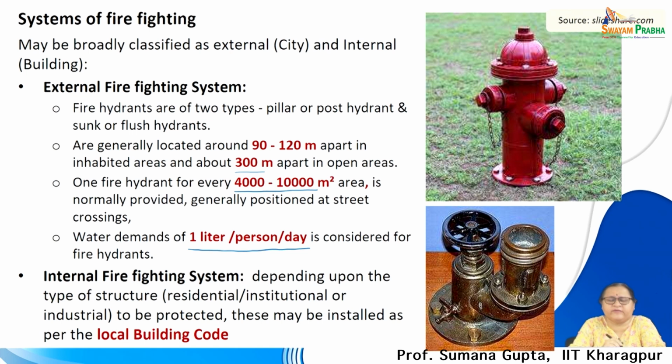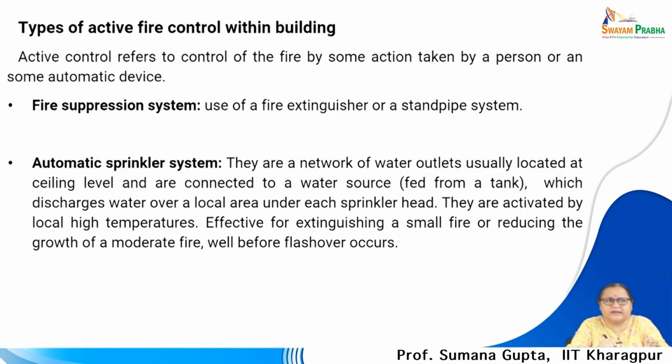However, the internal fire systems are independent of that, and dependent on the building infrastructure and whatever building water is there, and the supply has to be from the building until the fireman reaches the building. Even the firemen are dependent on the static water, which has to be maintained as mandated by the local building code. So, we must look into how we can include this system within the building.